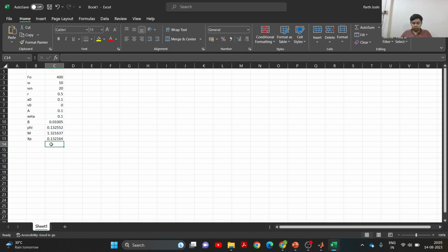So these are some of the quantities that we can calculate using this method. So let us move on to the next example. It is given that an industrial machine weighing 445 kg is supported on a spring with static deflection of 0.5 centimeter. And it is given that the machine has a rotating imbalance of 25 kg centimeter and the rotating speed is 1200 rpm. So it has been asked, what is the dynamic amplitude of the machine?